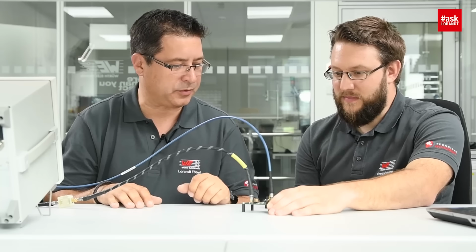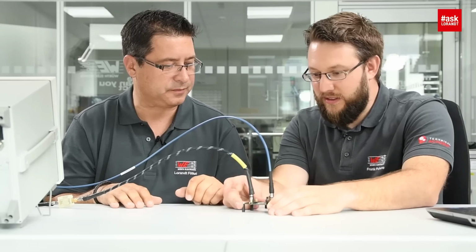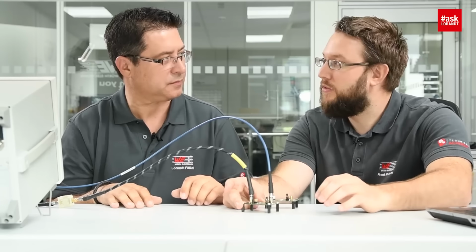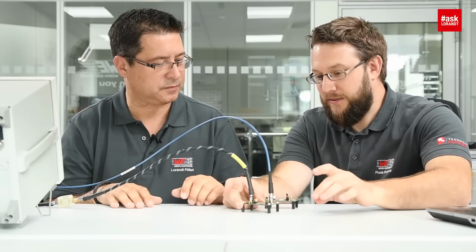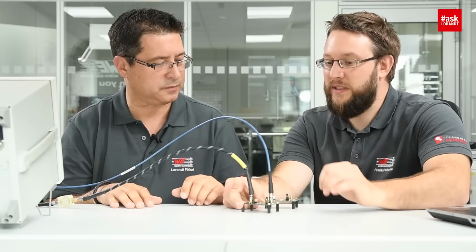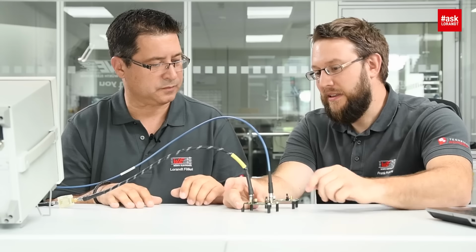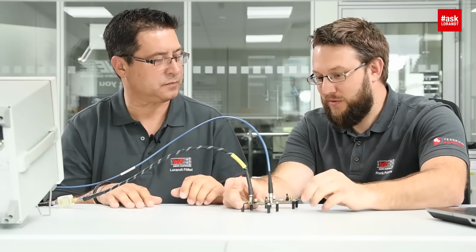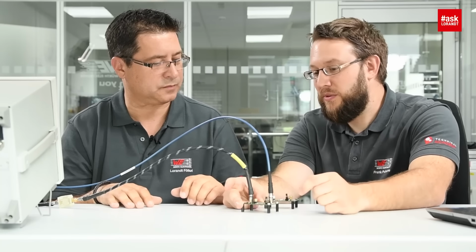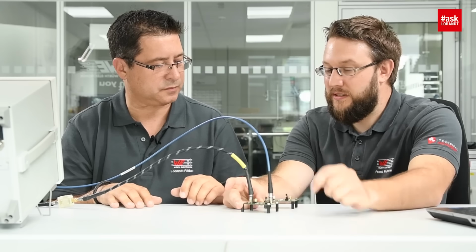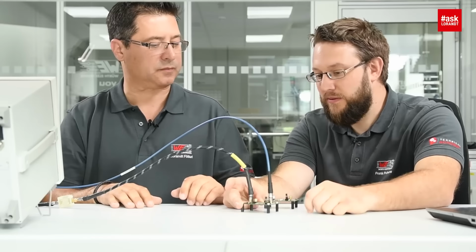I see you bring two boards with you. What do you have on the first board? The first board has the same capacitance value, 2.2 microfarad, and we change the voltage rating of the capacitor. Of course, we're starting with a class 1 ceramic to show the influence of this kind of ceramic. Then we have class 2 ceramic, X5R, X7R with 6.3 volt and with 25 volt.